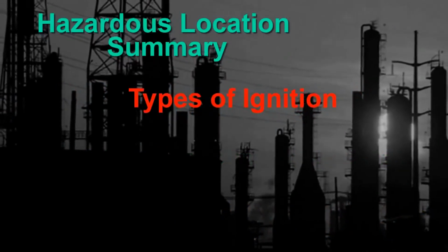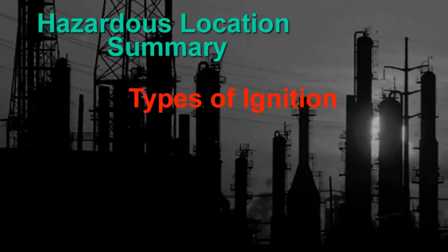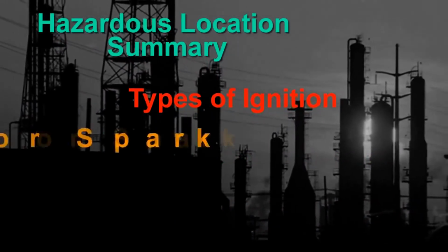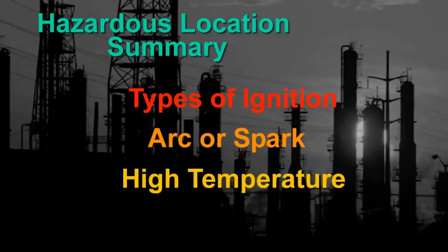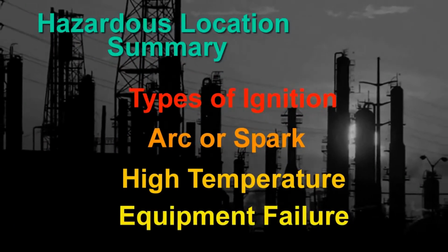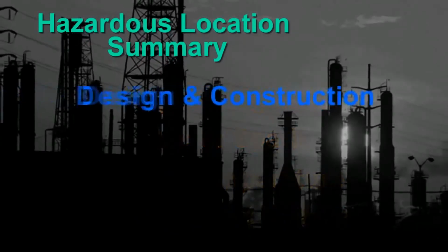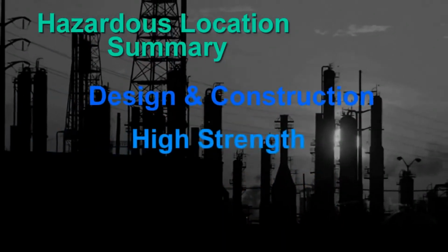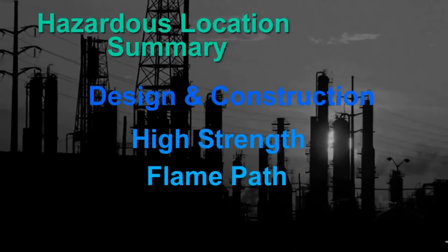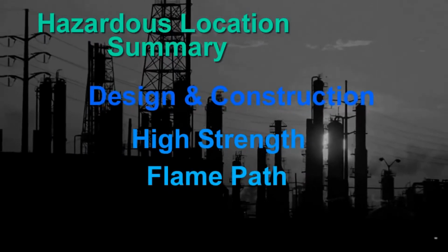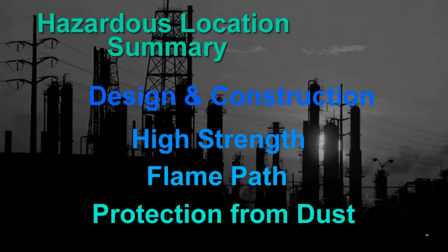All equipment within hazardous locations must protect against three predominant types of ignition: arc or spark, high temperature, and equipment failure. Within NEC-rated materials, the design and construction must have high strength, a path for explosive materials to be extinguished, or provide protection from dust buildup.